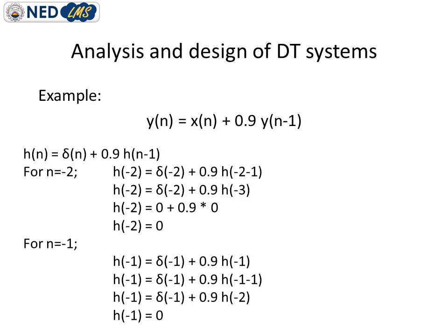Again, we can prove it mathematically also, that this system is an infinite impulse response system. By using the same strategy, we have to substitute different values of n in the transformed equation, and the equation is transformed in a similar way. y is replaced by h of n and x is replaced by delta of n, which is the impulse function.